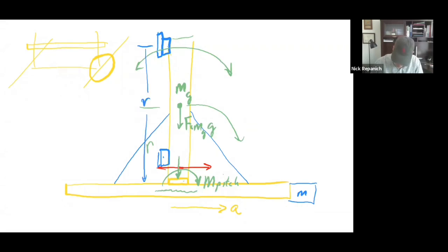And so then the pitch moment would be M A times R. In this case, it'd be M G times the acceleration rate times R, we'll call it R sub T. And then again, you'd look up what the manufacturer says that bearing set is capable of, compare that to what you're doing, and you'd get a factor of safety for that axis.